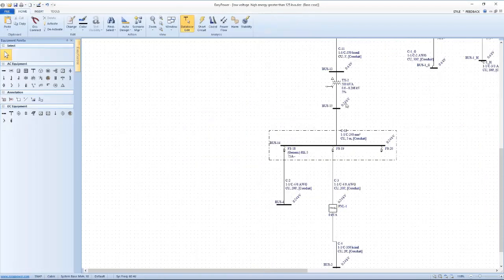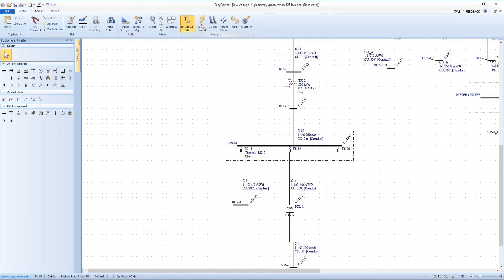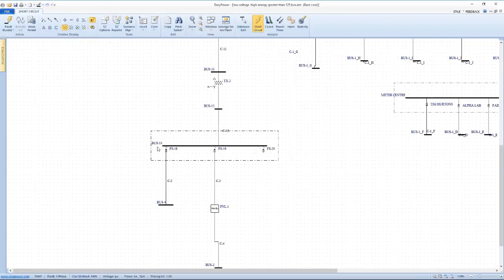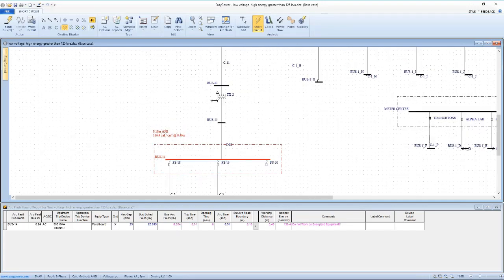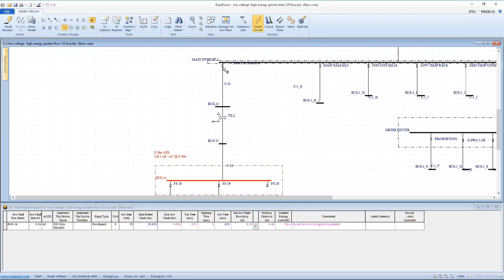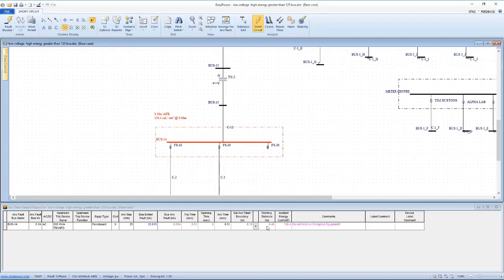All right, so the issue here is I'm coming off of a 208 volt panel, and if we look at how big this transformer is, it's actually a 500 kVA. So this system doesn't qualify for the time limit on the calculations. And so when I go out here and look at the incident energy, what we're looking at is bolted fault current of 20,000 amps. So there's a real 6,500 amps consumed in an arc. And we still have this issue of a trip time for the breaker, or the fuse in this case, which is in the primary side of the transformer. And that's what's causing my high incident energy for this bus.